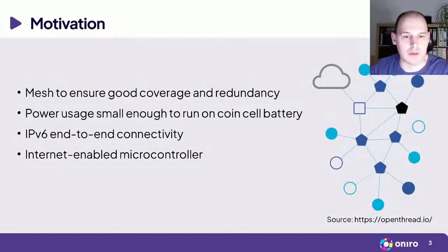And also about the power usage. One of the targets I had was using my controller with a coin cell battery and having enough power to run on this one coin cell battery for at least half a year or something like that. Depending on how big the usage is and how much data you're transferring, that can run a year or two on a coin cell battery. And that's not really possible with Wi-Fi right now. They're working on more power efficient standards for Wi-Fi as well, but right now that's not really comparable.